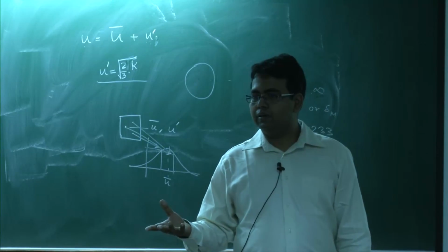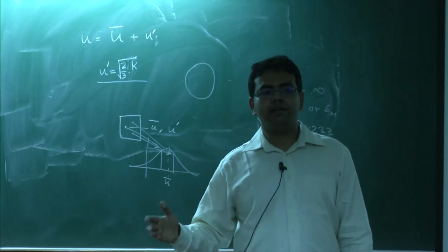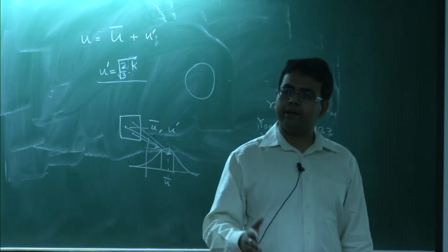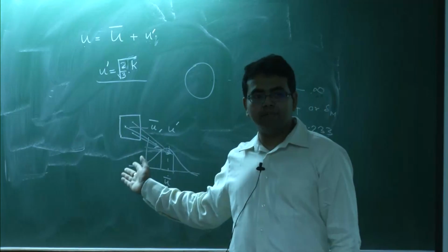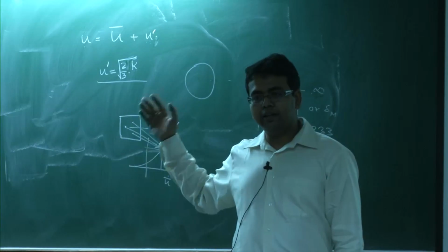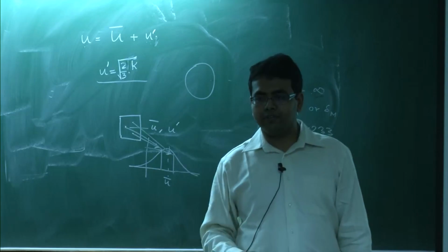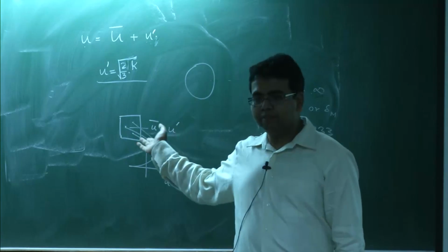The classical model used the mean temperature and mean concentrations to evaluate the evaporation rate, but ideally we should calculate the instantaneous temperature and concentrations, utilize them in the Spalding number expression, and calculate the evaporation rate, like what we are doing for the velocity.